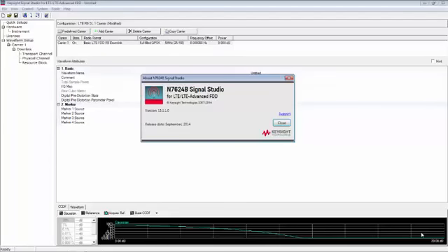the performance of a digital radio transmitter. A signal sent by an ideal transmitter would have all the IQ constellation points precisely at the ideal locations. However, various design imperfections such as carrier leakage, low image rejection ratio, phase noise, etc. cause the actual constellation points to deviate from the ideal locations.